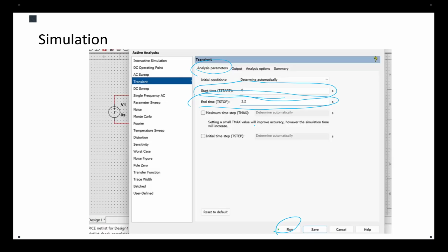It should be the same waveform that you see on the oscilloscope, where you already know how to find tau as 63% of the final value, and how to find the values for 1 tau, 2 tau, 5 tau. You know what I'm saying? So same goes for the RL and RLC.